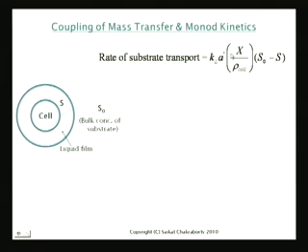So K_L times a' would then be per unit volume. Okay, the unit of this would be per unit volume. So K_L times a' times X over rho_cell would be for a particular given volume. So this would be the mass transfer coefficient times the difference, of course, S0 minus S. So this is the amount of substrate transport.